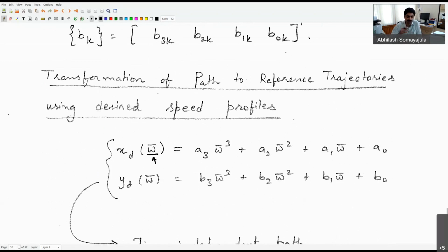Notice that when we want to talk about trajectories, we are really more interested in the speed of the vehicle. So some desired speed of the vehicle at certain waypoints will now start figuring into the account. Because at certain points we want to be at certain times in a trajectory tracking problem. So the speed profile is particularly important, and you will see that this mechanism which we used for the path generation allows us to specify the speed profile independent of the path. Which means that if I were to look at an offline path planner, it can generate the waypoints and the path as well.